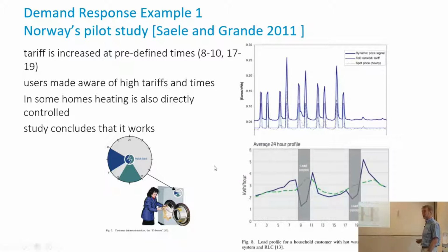Exactly. So that's one of the issues of demand response, is exactly this, right? It's fairly easy to reduce consumption during a short period of time, but what you expect when you do this is what is shown here. Anticipation, that may occur here. This is in countries where people anticipate, Norway, obviously. And rebound. The rebound effect is the fact that after that you heat more.